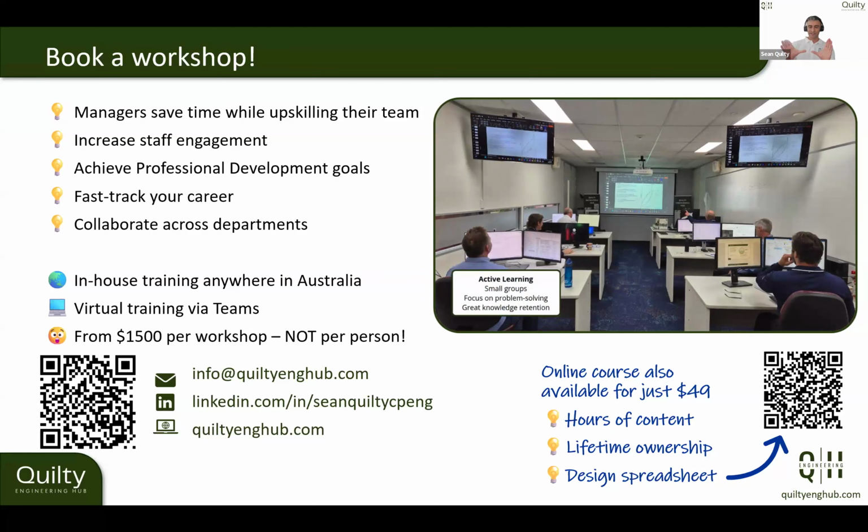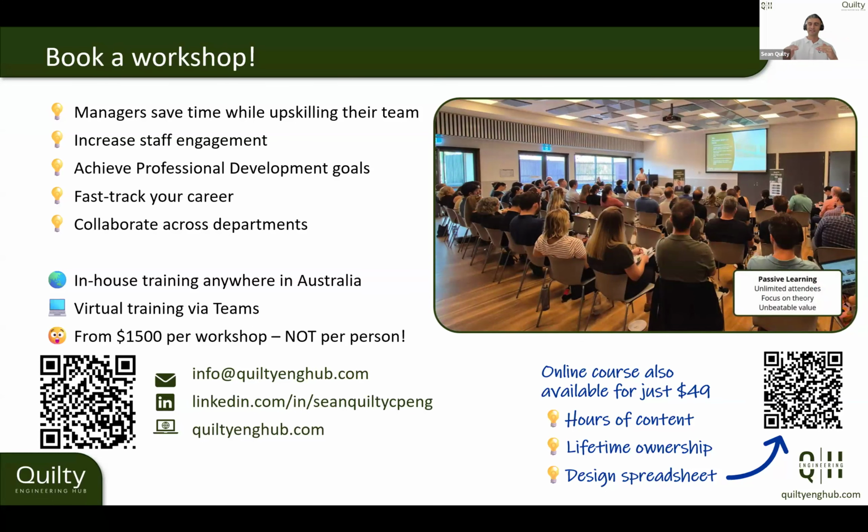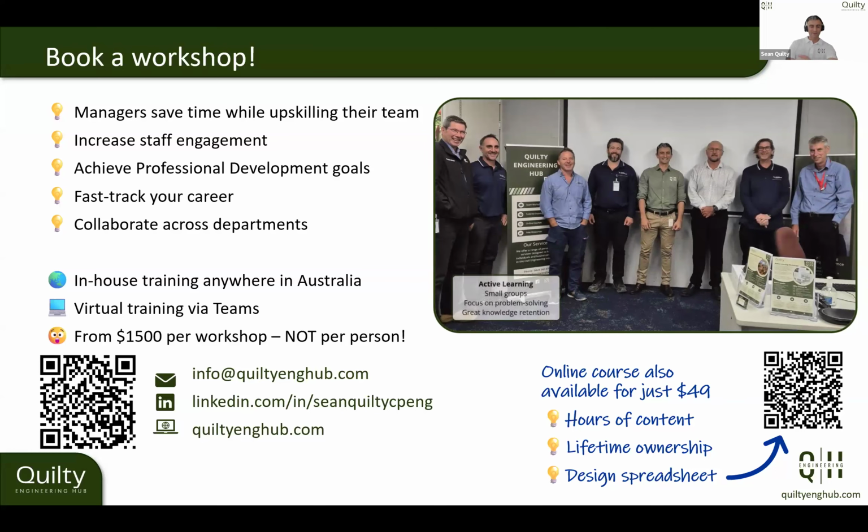So with that channel design, your Manning's value becomes really smooth. All of a sudden, you've got a really high velocity, and you've got to keep that velocity down. So then you have to look at your channel and maybe make it wider. The depth drops, the velocity drops, and it's acceptable. So just after construction, it'll handle. During maintenance, when they strip that back, it'll handle those flows as well.